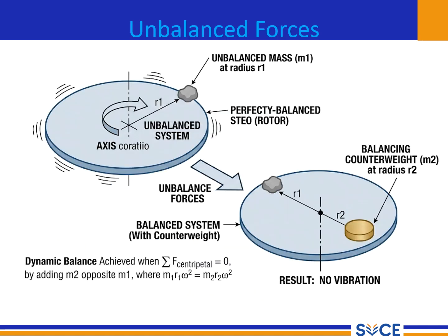In machines, moving parts generate inertia forces. If these forces are not properly balanced, you see that this is a rotor. In the rotor, if the mass is equally distributed, then the inertia force is also equally distributed. If the masses are not properly balanced, then the unbalanced force will create unbalanced inertia, which will lead to vibration. This vibration will affect the shaft or bearing, cause noise, and continuous vibration will produce wear of the components and reduction in machine life.